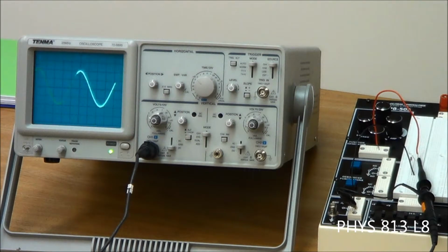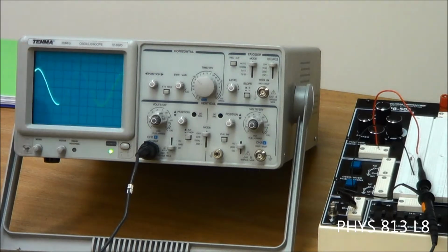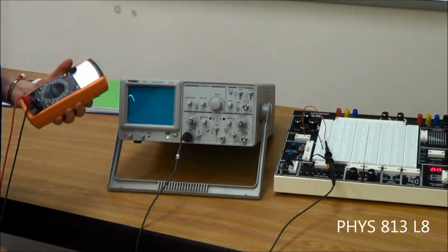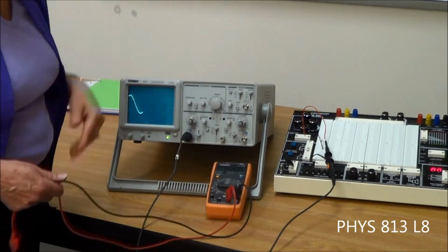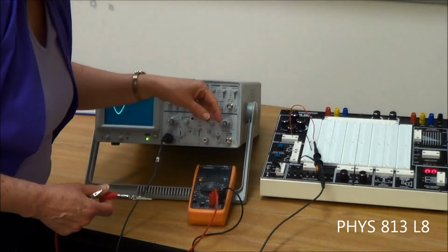Okay, then I have it where you can fill this out. So we have this on 2 milliseconds per centimeter. We need 5 divisions. Then we need to measure the voltage, and here it is 2 volts. Then we're going to use our meter. So we have our orange meter. Make sure you have the one that measures voltage. I have the black in the common. I'm going to just sit it here. Oh, turn it on. And after I measure it, I'll hold it up where you can see it.